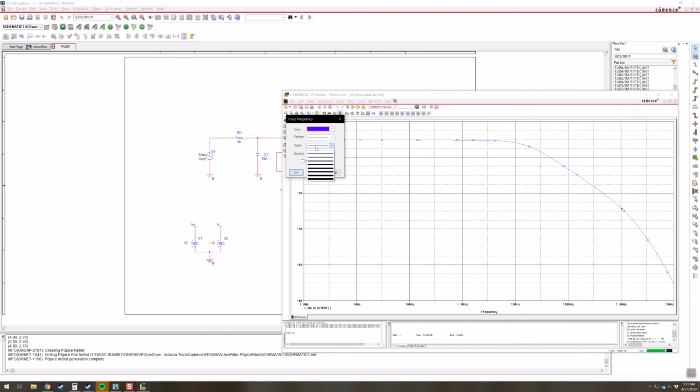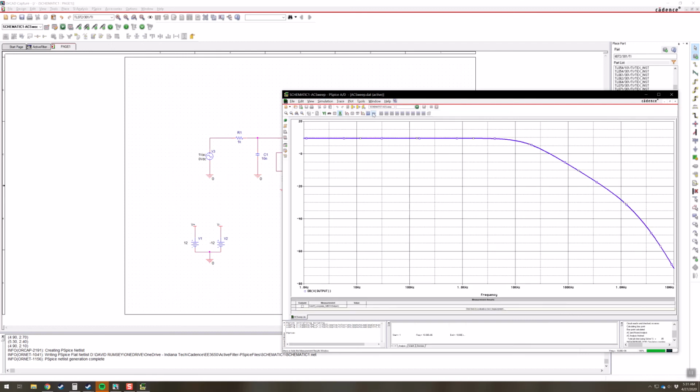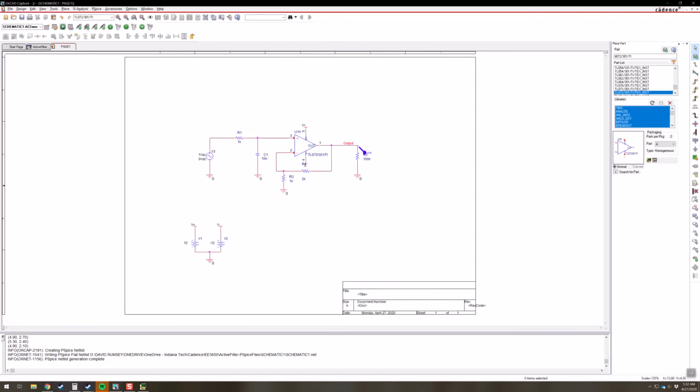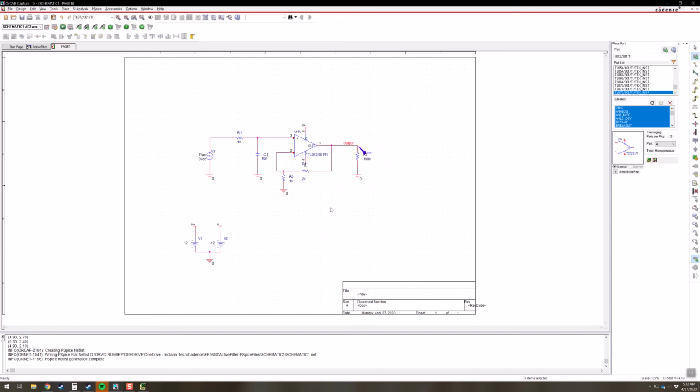Oh, I know what's going on. We have the exact right cutoff frequency. You guys who are watching this video may have already noticed this. Yeah, we get 15.857. When I had my calculator up here and was computing it back in the day, I forgot the formula. The formula for computing your frequency is, of course, 1 divided by 2 pi times R times C, where those are the inputs. What did I do?